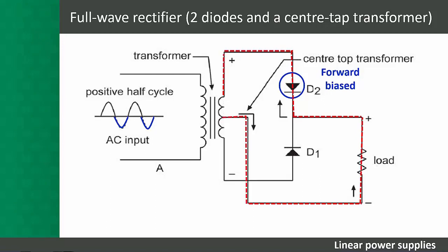From this, we can see that current flows through the load resistor in one direction only, for both AC half cycles, so the full AC wave cycle is used. The output waveform that is obtained is shown here at the load resistor. This process is called full wave rectification, and AC has been changed to DC. Let us now watch how this circuit would be constructed on a breadboard.